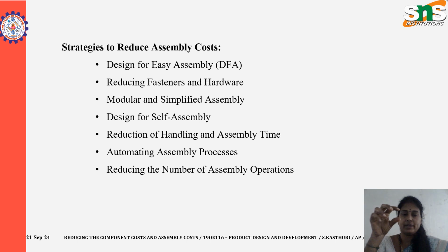Modular and simplified assembly. Design components and some sub-assemblies in modular form so that large sections of the product can be pre-assembled and tested before final assembly. Modular designs reduce the number of parts to be assembled during final assembly, speeding up the process and reducing the labor cost.